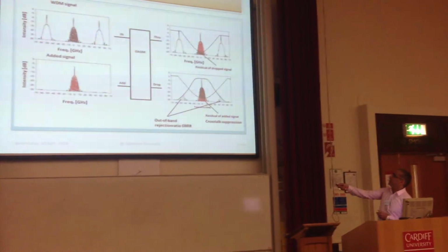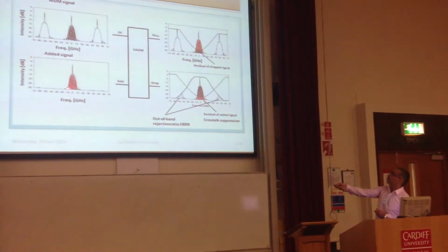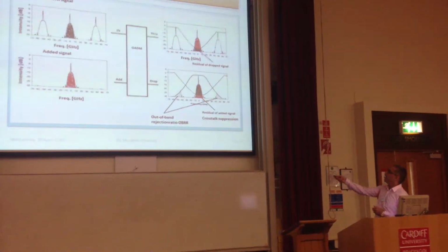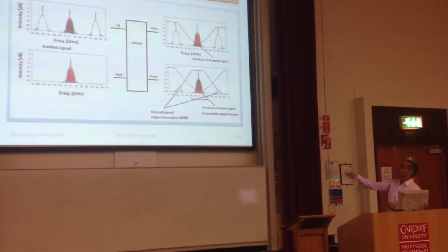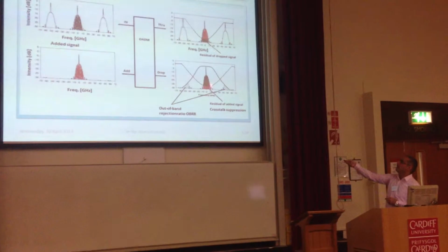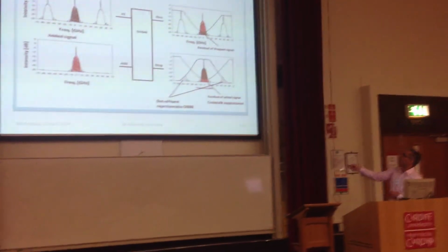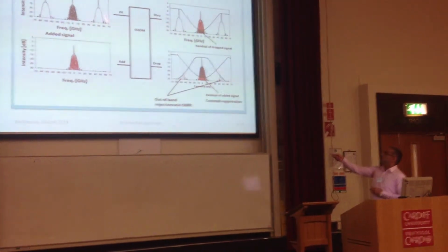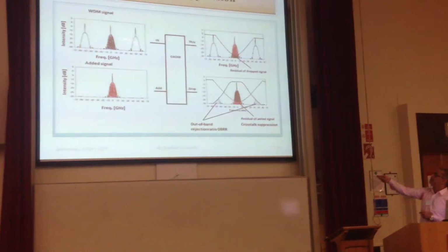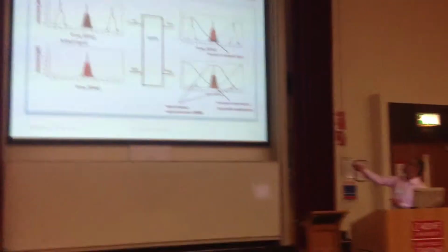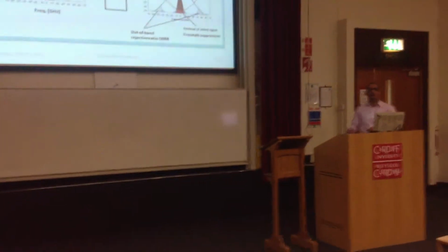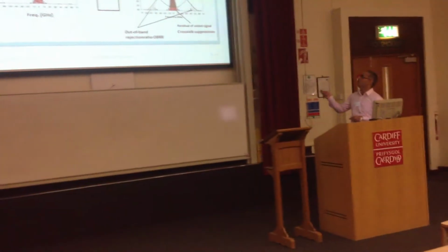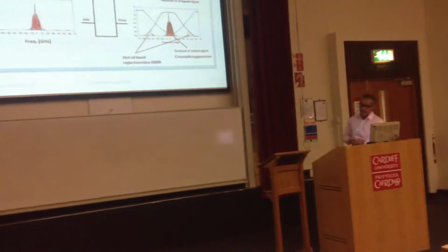One is from the added signal with the same wavelength, and this we can decrease by increasing the crosstalk separation. This is called intraband crosstalk. The other type of crosstalk comes from the adjacent signals of different wavelengths, and this will be decreased by increasing the out-of-band rejection ratio of the filter.